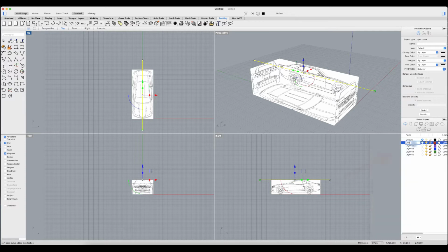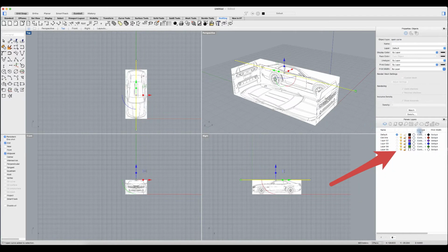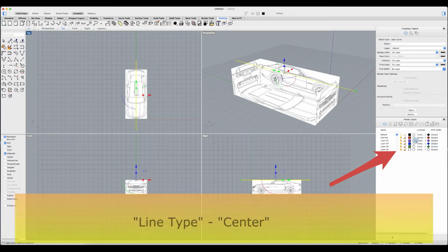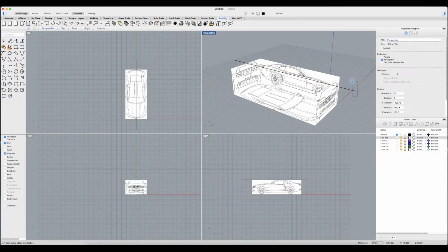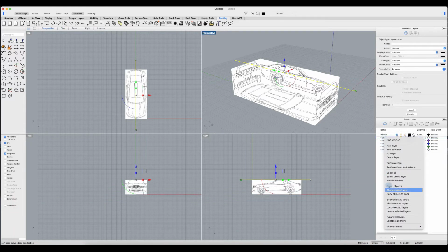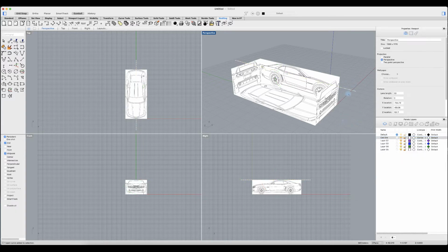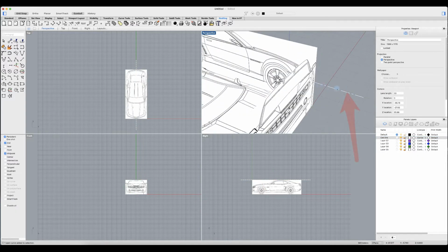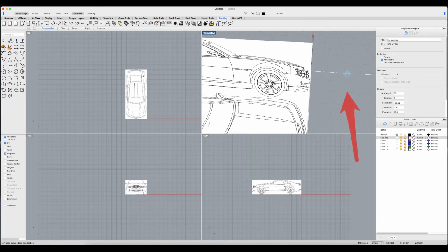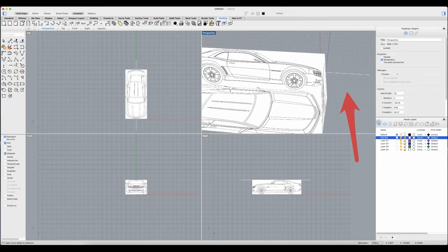real. So we're going to retitle this as center line, and if I expand, you would see our line type. If you click on that, you just want to switch that to center. It provides the standard visualization of that center line. Let me select that, move that now into that layer, and you could see the line type shows already that center, and I would lock that down.